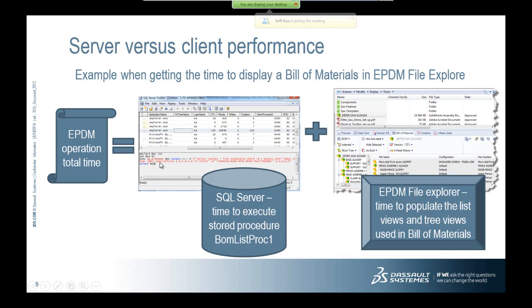Basically, you can see here the procedure for the BOM list processor, and the difference between this time and the one that you measured is basically the time it takes for the client application, the PDM file explorer, to populate the list for the bill of materials for the component you selected.